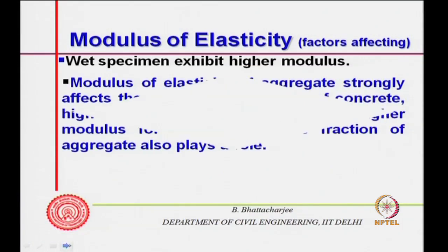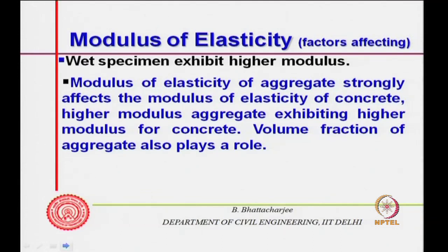water instead of air. Modulus of elasticity of aggregate strongly affects the modulus of elasticity of concrete. Higher modulus aggregate exhibits higher modulus of concrete, and volume fraction of aggregate will also play a role. That is what we have seen from our previous formula.